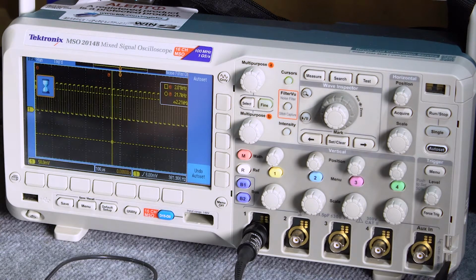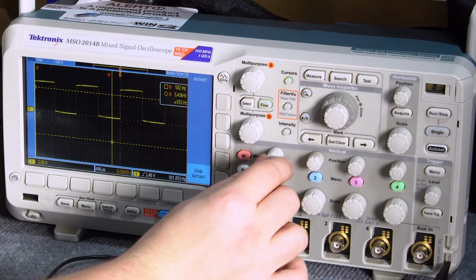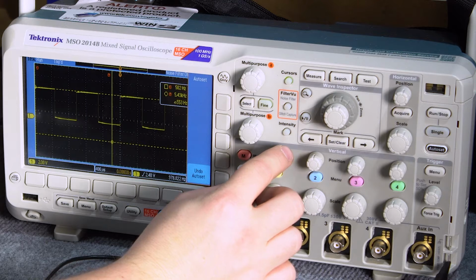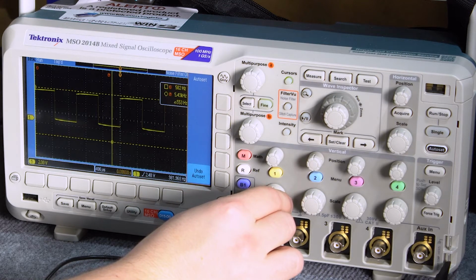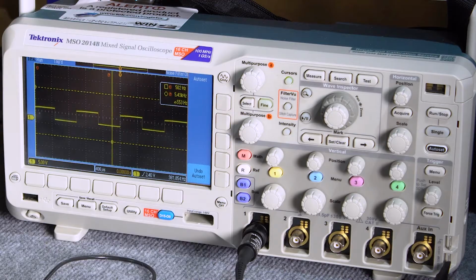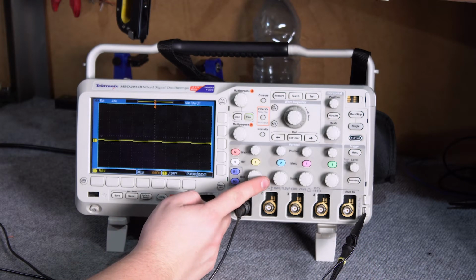Their inputs have a high resistance, in order of mega ohms. Therefore, they can overload circuits, and voltage probes should be connected in parallel like in a voltmeter. These are the most common ones, but sometimes we can see current probes which are switched in series. Oscilloscopes usually consist of 2 or 4 channels.